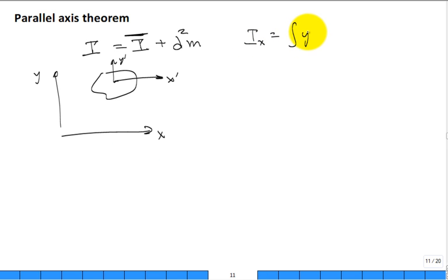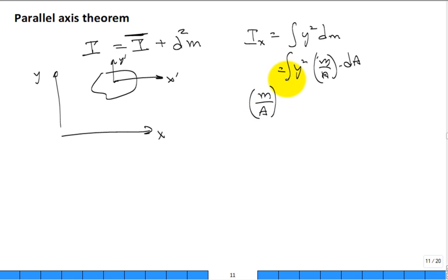That's the integral of y squared dm, mass per unit area times dA. It's like an area density instead of a volume density. Mass per unit area times dA will give us that dm. All right, then y squared. Well, we're not having a different density as it changes location, so that's constant. That can come outside that integral. And so basically it boils down to y squared dA.